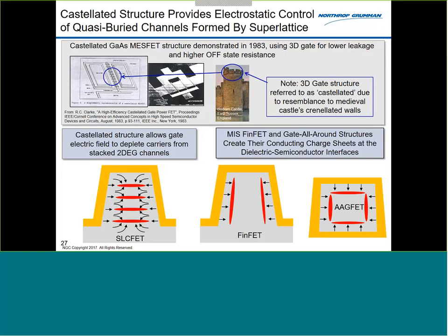But I don't get any gate leakage through there, so it's nanoamps of gate current during all operations. The maximum time that you see gate current in ours is when you go to high negative bias, just because you're at negative 14 volts or whatever. But in all cases we're talking nanoamps per millimeter, so it's very, very tiny. I hate to cut this off, but I'm just teaching.